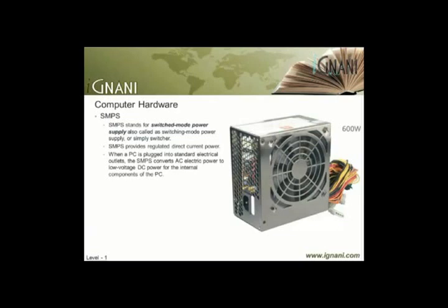When a PC is plugged into standard electrical outlet, the SMPS in the computer converts AC electric power to low voltage DC power for the internal components of the computer. It also regulates the voltage to eliminate spikes and surges common in most electrical systems. Power supplies are rated in terms of the number of watts they generate. The more powerful the SMPS, the more watts it can provide to components.